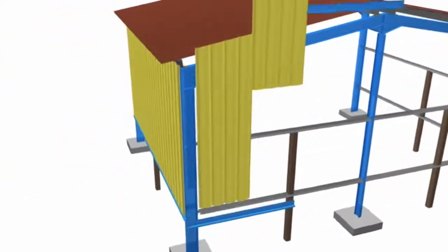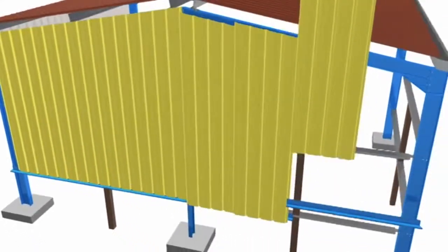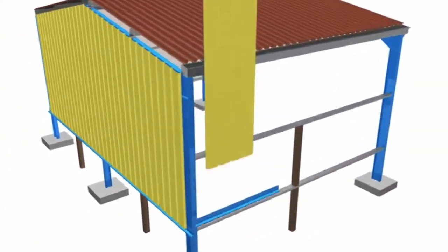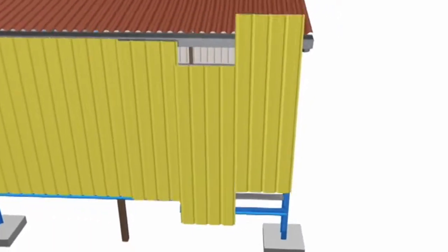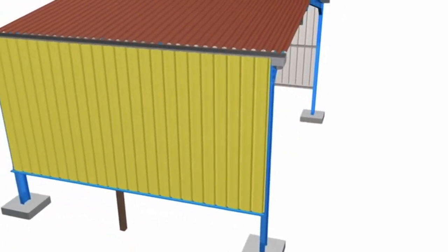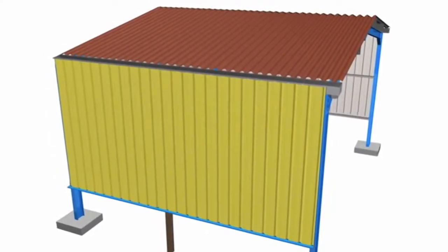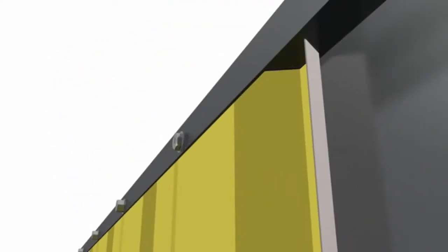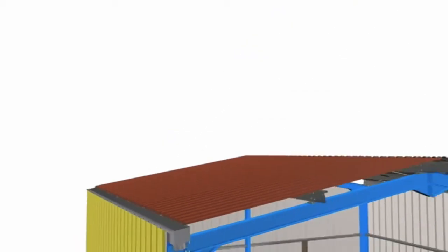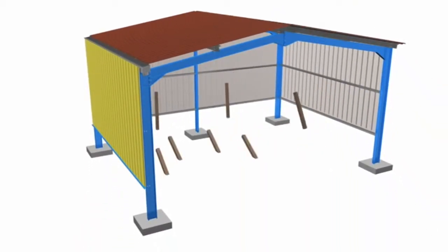In case 1, the design member which was chosen was 150 UC 14.8, as it had the ability to hold N maximum, which was 112.629 kilonewtons. However, the first choice was not acceptable as the L buckling was not safe when buckling out of plane. So the column was changed to 150 UC 23.4.